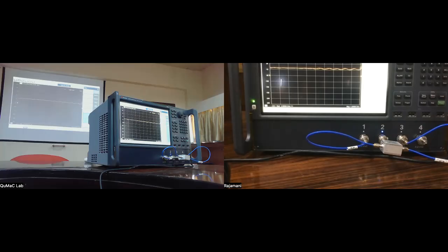It also changes the packaging you have to make. If you have to make things work at very high frequencies, you usually have to make things smaller and compact. The connections have to be as short as possible. So that's what determines whether it remains the circuit you have drawn. But a voltage divider is a voltage divider, right? It doesn't depend on whether it's an AC signal at the input or not. What I'm saying is that it depends on the type of material you use to construct that resistance. It's not just that the resistance itself will change. That just means that it's a different voltage divider still composed of resistive components.